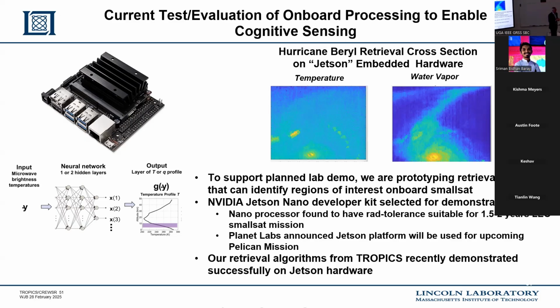Yes, there are people developing lenses for this application. Those also have their drawbacks. With a lens, there's potential for standing waves between the receiver and the lens, so you have to worry about that. It's also much harder to enable an electrically scanning system with the lens. Those are the drawbacks, but there are people developing lenses for millimeter wave.